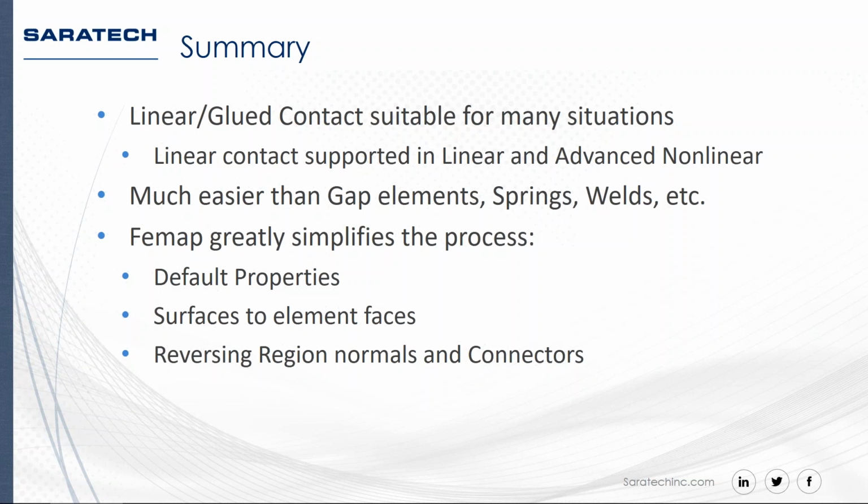And the nice thing is that Femap really simplifies the process for you with the default properties when you're defining either the glued or contact property. Also, just being able to use surfaces to define those regions, and it automatically applies it to the element faces for you. And also the fact that you're able to very quickly reverse the normal directions of the regions and also even flip the connectors as well if you want to swap the master and slave.